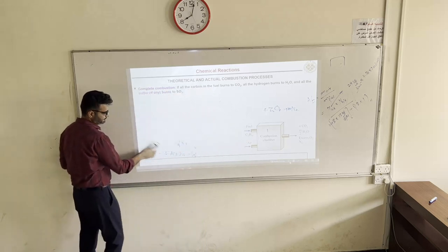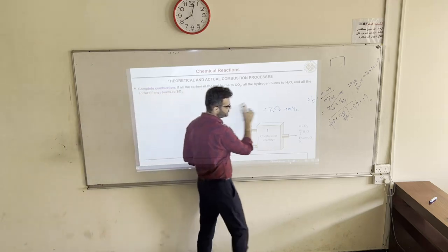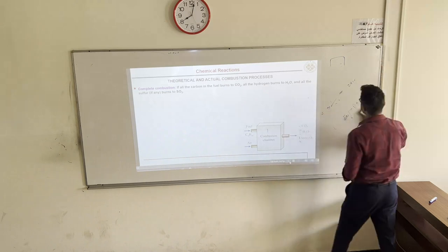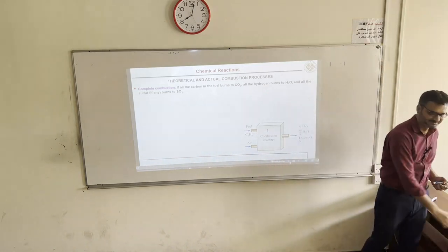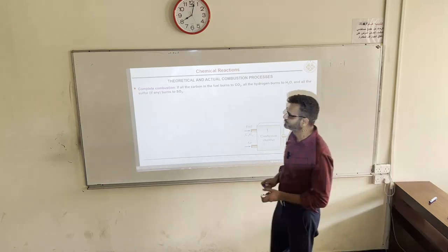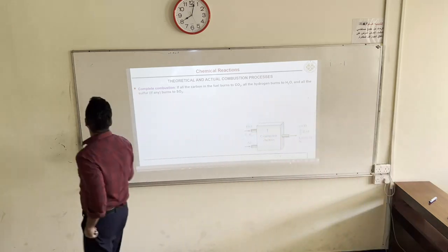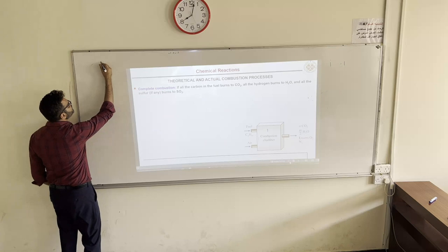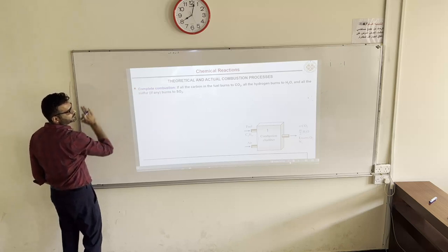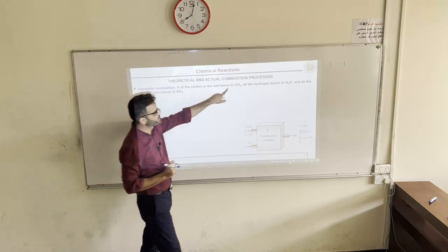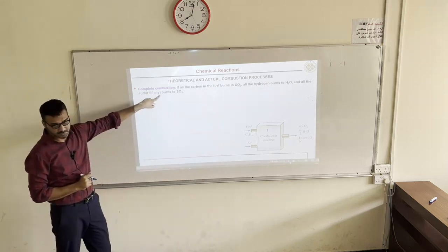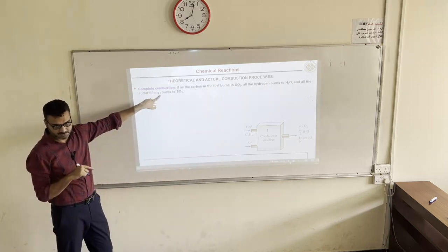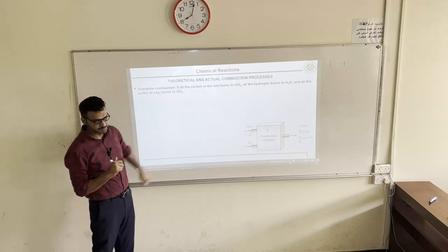What does that statement mean? Complete combustion. Explain more. So that is the definition: if the carbon in the fuel burns to CO2, all the hydrogen in the fuel burns to H2O, and if there is sulfur present, it must burn to SO2.